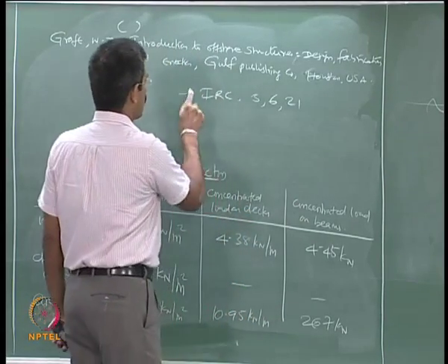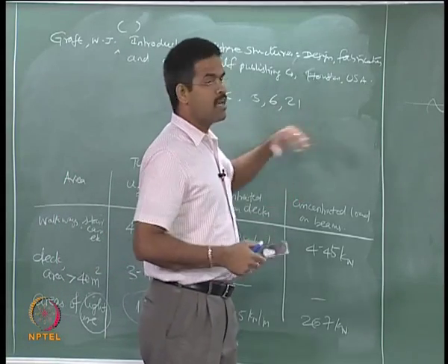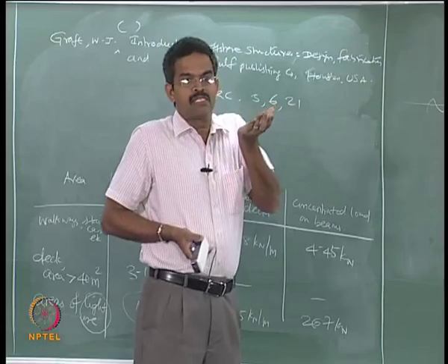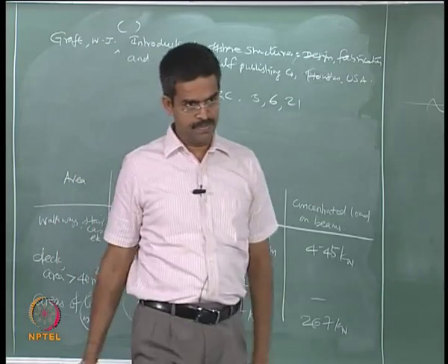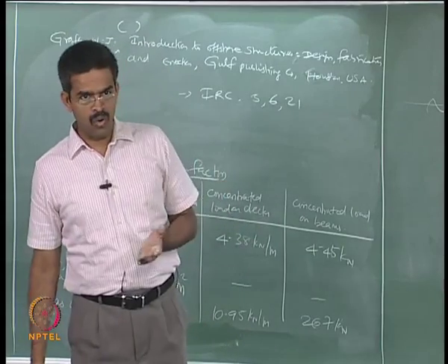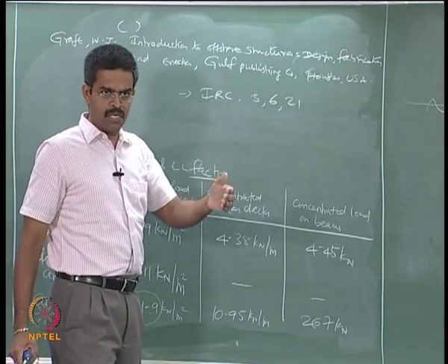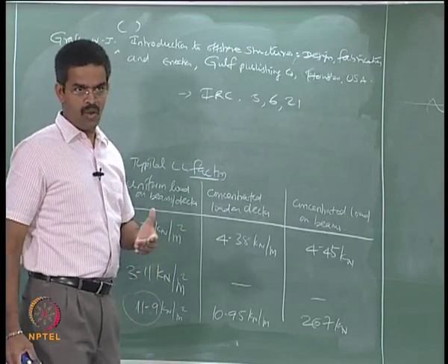In all these codes they say that the impact load caused by the vehicle movement will be enhanced by a multiplying factor on the live load. So this practice is common in almost all codes which speak about impact loads. A similar concept is adopted in marine structures design also.